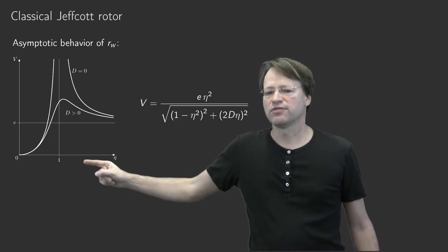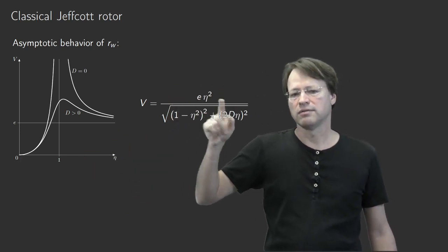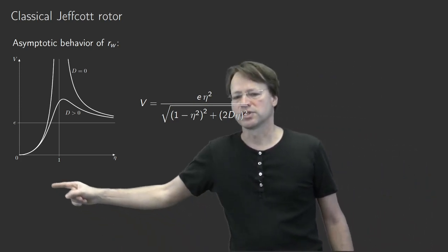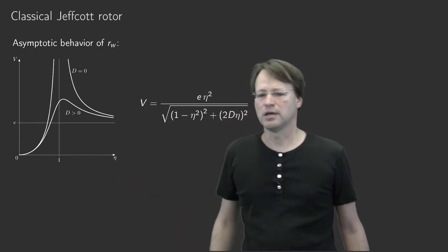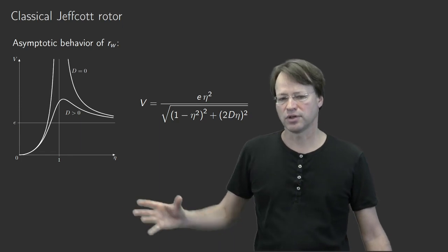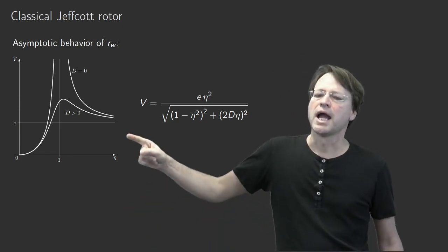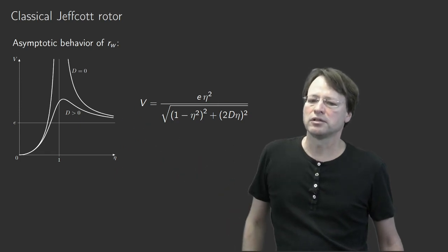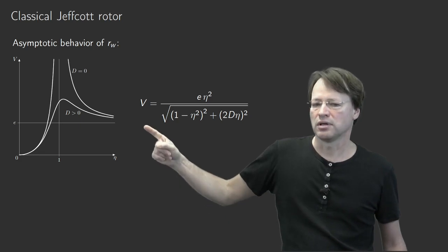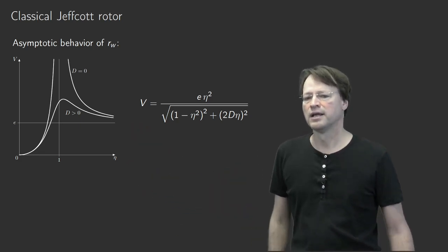That magnification factor, keep in mind that in the numerator we have the product of E times epsilon squared. So it starts at 0 for very low values of eta, so very low rotational speed if you keep the system parameters and therefore the natural frequency constant, and moves then to a value of E in the asymptotic case that eta tends to infinity.